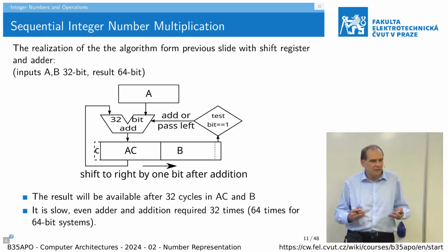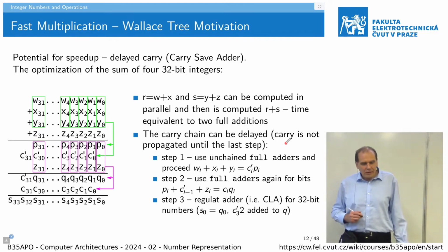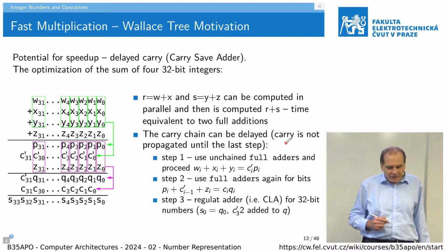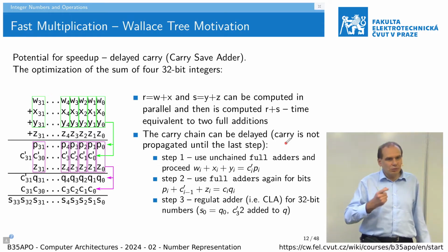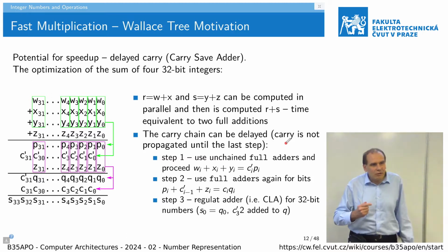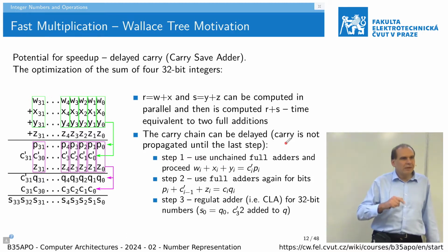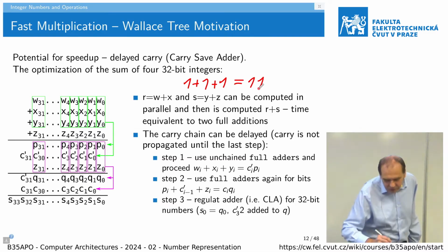It is an AND gate. So what we can do with this problem, we can look at our others, which we have implemented before, and we can see that a full adder provides us 2 bits of the result, but cannot overflow to the third bit, to bit number 2, because 3 times 1, which is the maximal value, is a 3.